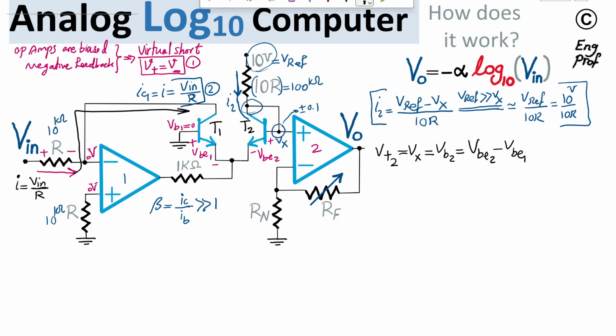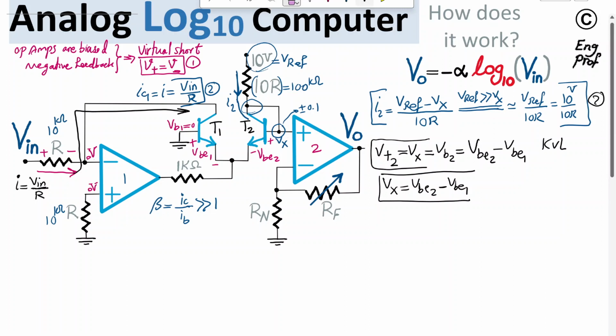So that is the KVL, or Kirchhoff voltage law, one of the circuit laws that I just wrote. As a result, I can say Vx is equal to just VBE2 minus VBE1, equation 3.